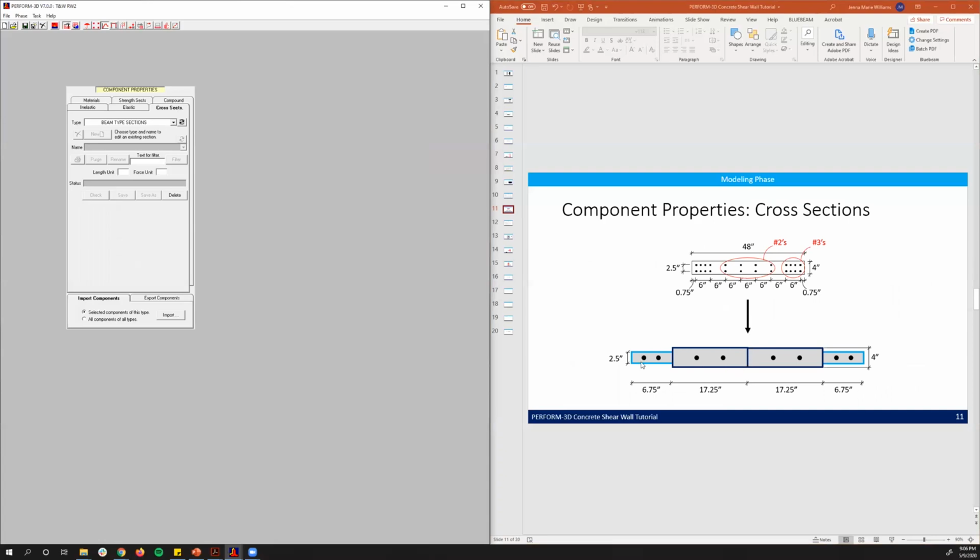We've decided to keep the confined sections on the end and unconfined sections in the middle. So all of the confined concrete on each side is lumped into 2 pieces of rebar. And same thing in the middle, the unconfined sections. There's four bars in each of these sections, and they've been lumped into just 2 bars because we can't model the 2 layers of rebar.